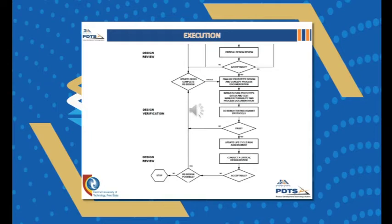The developer shall design the concept process for manufacturing and inspection of the prototype under development with the outsourced manufacturing company. All concept work instructions, inspection, and test instructions, etc. should be defined. The manufacturing requirements in respect of the following elements will be considered and recorded: facilities required, equipment required, machinery required, processes required, inspection and testing equipment required, workmanship standard required, manpower and skill, cleaning method required, packaging method required, etc.